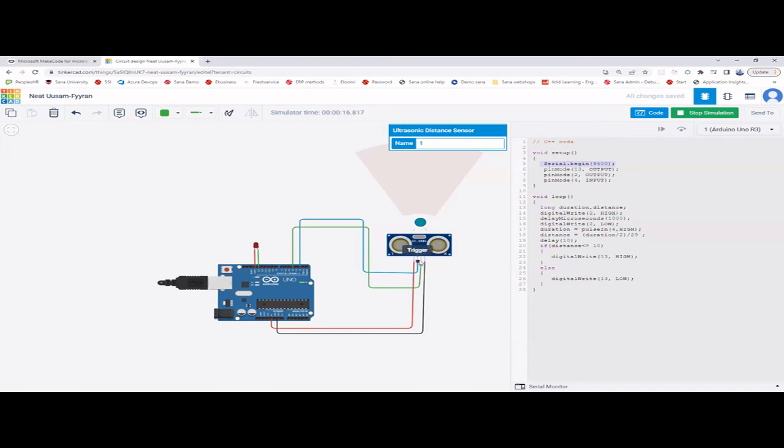So hope you know the trigger is the input for the sensor. But 4 is the input for the Arduino board. Can you see it's connected to the echo in the sensor? So echo is the output from this sensor, but it will be taken as the input for the Arduino board. That's why 4 is the input. Right? So don't get confused with the input and output. For the program, it's from the Arduino board's point of view. In the sensor, echo means output, trigger is the input.